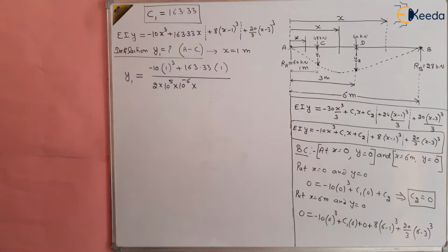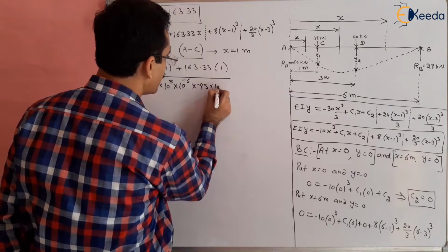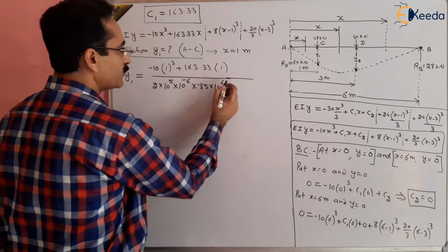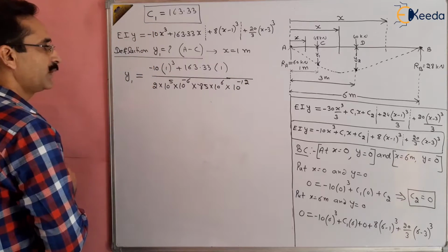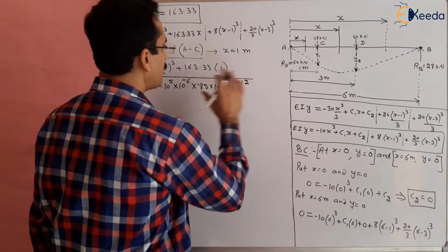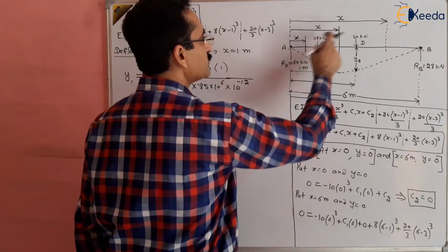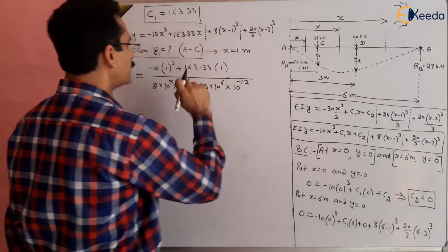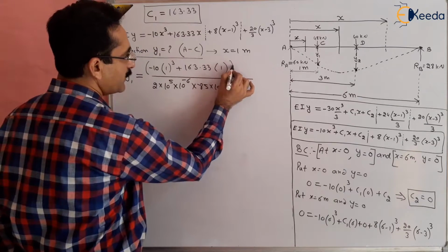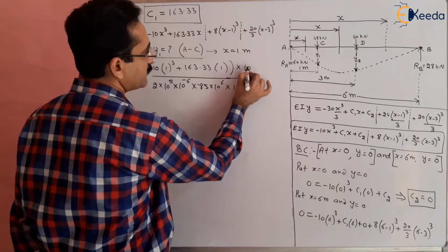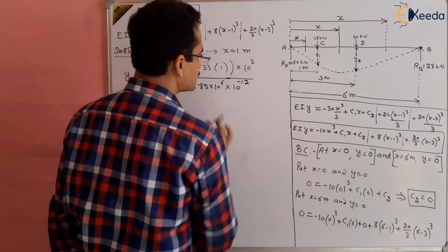So I is 85 multiplied by 10 power 6 millimeter to the power 4. So it will become 10 to the power minus 12, right? This much, but here this is given in kilonewton. The load was used in kilonewton, so that kilo should be replaced with 1000 to get the answer in SI unit. That's why I am multiplying it here by 10 power 3. The answer will come now in meters, right?